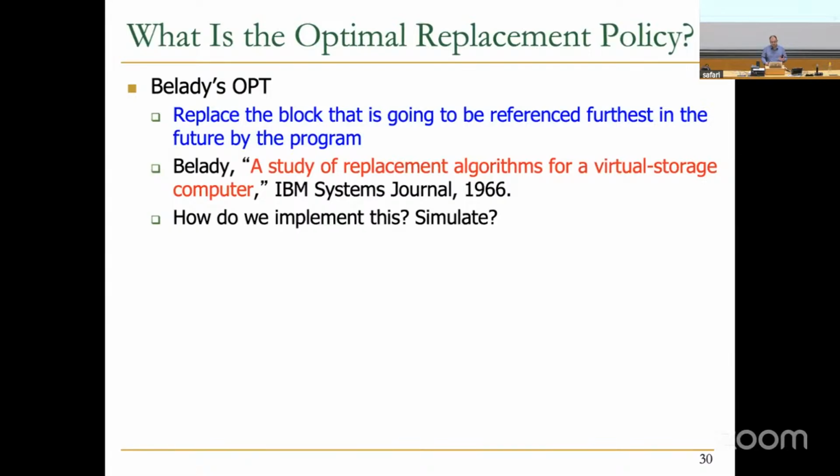And this can be used to show the gap, for example. If you consider Belady's replacement policy the best, the optimal one, by the definition of optimal, which in Belady is the lower miss rate, then whenever you want a lower miss rate, Belady's OPT is the optimal one. So people have tried to implement or simulate that in order to show the gap, or the room, that you can improve your cache by using better replacement policies.